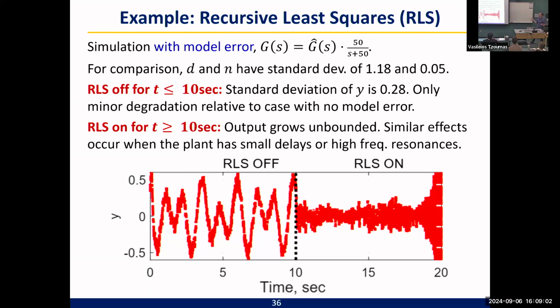Great, okay. On the other hand, this thing works great if I know the model. I added just a little bit of model uncertainty, and it starts going unstable. If I add just a little bit of time delay or a little bit of high frequency resonances, it's very easy to cause this to go unstable. So that's the crux of the issue.